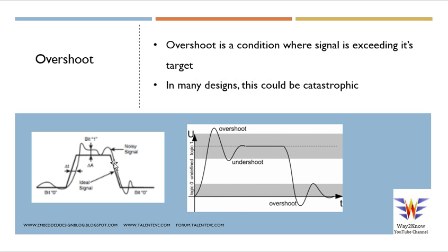So because the IC is characterized as per the specifications provided in the datasheet, any voltage or thermal or anything beyond its characteristics or specifications could cause an issue which is unpredictable basically, because even it's not tested by the vendor itself, right?